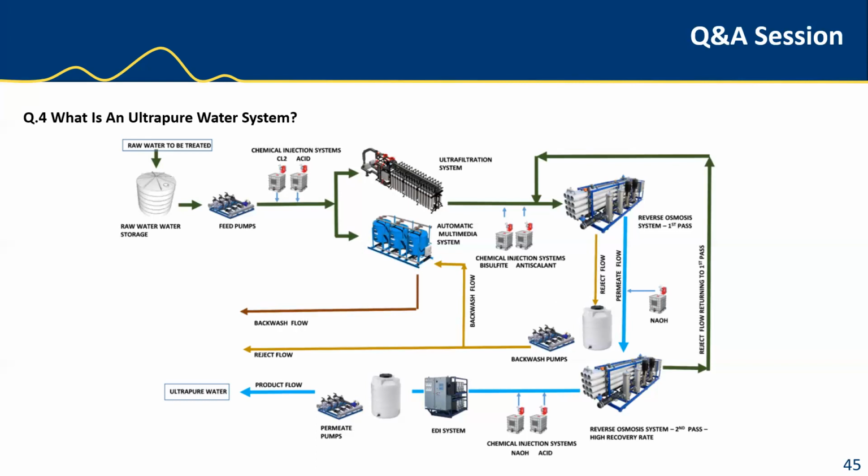So there are about 3 stages in an ultra-pure water system: the pre-treatment, the primary, and the polishing. In the pre-treatment phase, you get the basic purified water. Depending on your system, you may use two-pass reverse osmosis, demineralization and reverse osmosis, or high efficiency reverse osmosis. Additionally, the water is cleaned of any large debris, easily caught in a filter. This phase also might incorporate activated carbon or sodium bisulfite to dechlorinate the water as well.